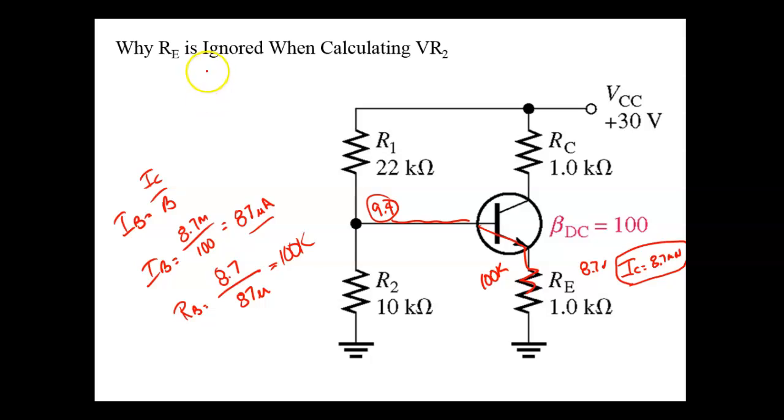Okay, so technically the actual bottom circuit would be 10K in parallel with 100K. So what's 10K in parallel with 100K? What would that resistance be? You can use product over sum. You can use sum of reciprocals, reciprocal of sums. About 9K or something.